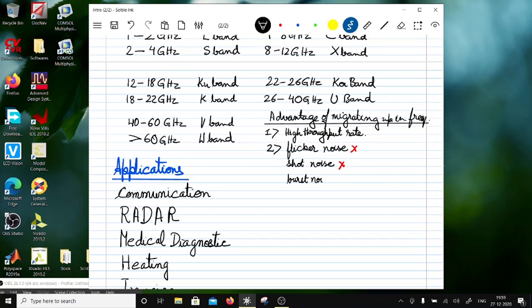Okay, so this burst noise is due to the heavy ions. For example, if you do a metal implant to increase the conductivity. If you take a polysilicon, on its own it is very resistive, but if you do an ion implant on a polysilicon, it becomes a conductive poly. But the problem with that conductive poly is that there is a heavy metal ion. So this usually results in a noise which appears like a burst, and this is usually in the kilohertz range, right?